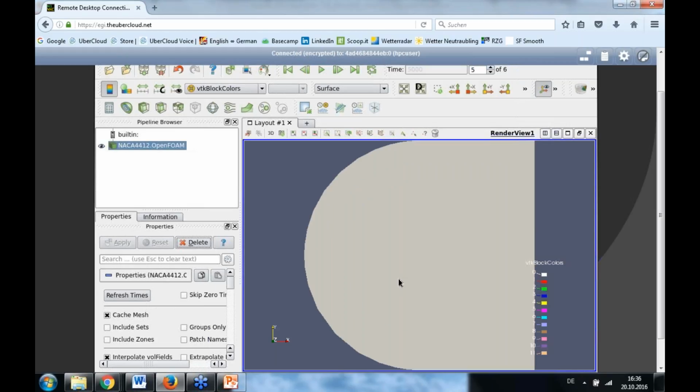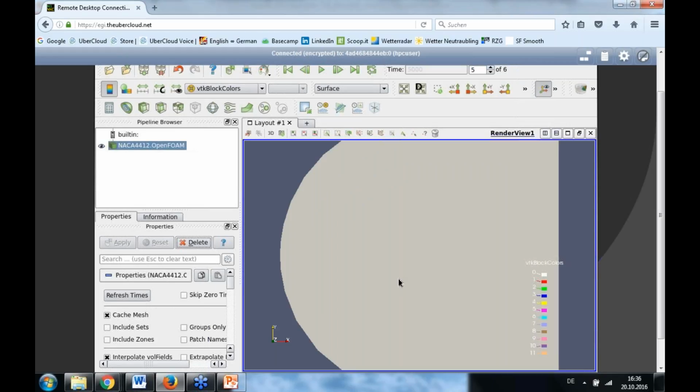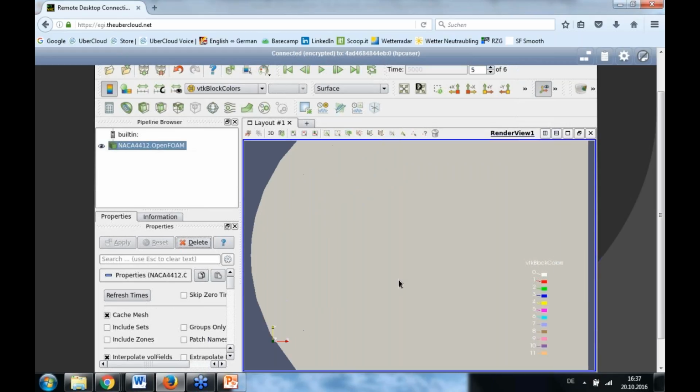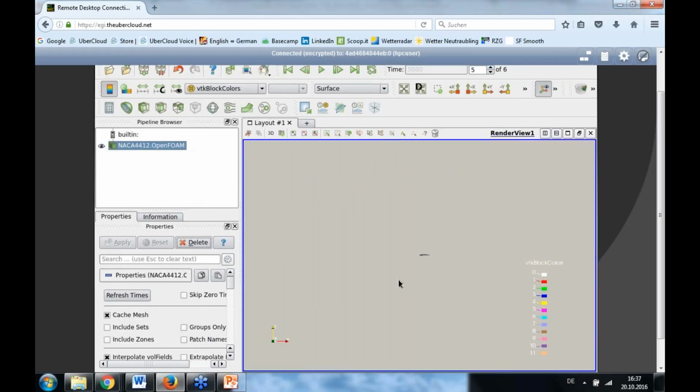It has to be large, otherwise the airfoil would interfere with the boundary conditions too much, and especially when it comes to transonic flows, shock waves from the airfoil would be reflected from the boundary condition and get back to the profile, and so that's disturbing the physical solution. So that's why. But I zoomed in, as you have seen, and for example, I can see the mesh